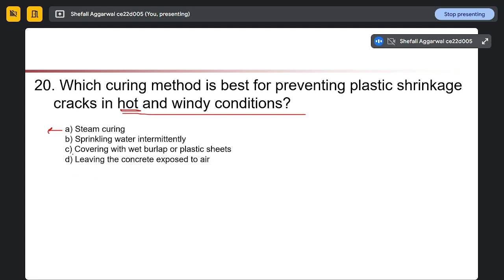So if this is our normal concrete matrix, if we have a high strength concrete, what will happen? We will have a very strong matrix, the pores will be very few, and the bond in the concrete matrix will be very strong. So in this type of concrete, firstly, the aggregate will break through, and the cracks will form through the aggregates, not through the cement paste.